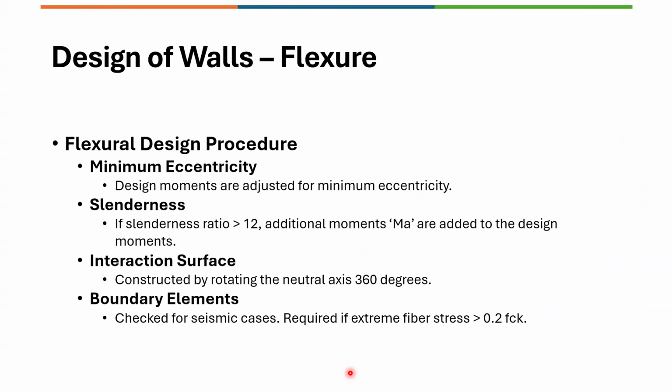So the design check also includes the minimum eccentricity, the slenderness, and it generates the interaction surface, and boundary element requirements are reported for the seismic case.